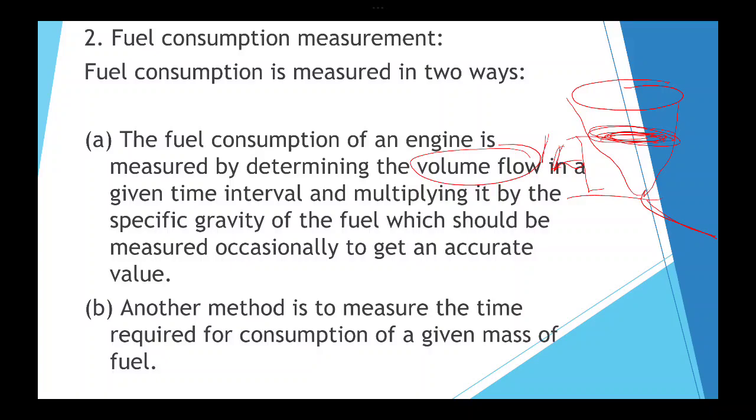So this 1 liter will be the input of your fuel tank. Then you start your engine for about 10 minutes, and after 10 minutes you compute the fuel consumption by taking out your fuel again, measuring it, then dividing by the time. Then you will have a unit of liters per second. That's your fuel consumption unit when you are in volume.